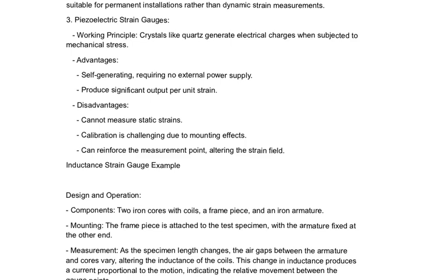It is self-generating, requiring no external power supply, and produces significant output per unit strain. Disadvantages: it cannot measure static strain. The calibration is challenging due to mounting effects, and it can reinforce the measurement point, altering the strain field.